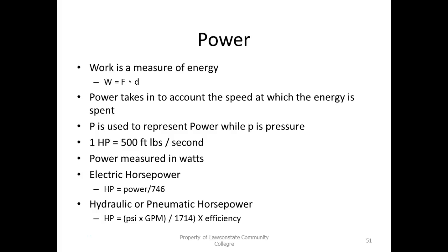But when we look at the nameplate, you'll see it gives you not only a horsepower, but it'll give you what we call the full load current, which means if it's a 5 horsepower motor, that's how much current it'll pull if it was developing 5 horsepower. And then it'll give you the voltage that the motor is designed to run on. They should come up to be fairly the same, but they're not, because we're going to compensate for the efficiency of the motor. So usually when you multiply the current and the voltage, you're going to come up with more over here than you actually get. So you might calculate 5.3 horsepower, and it's a 5 horsepower motor. Okay.